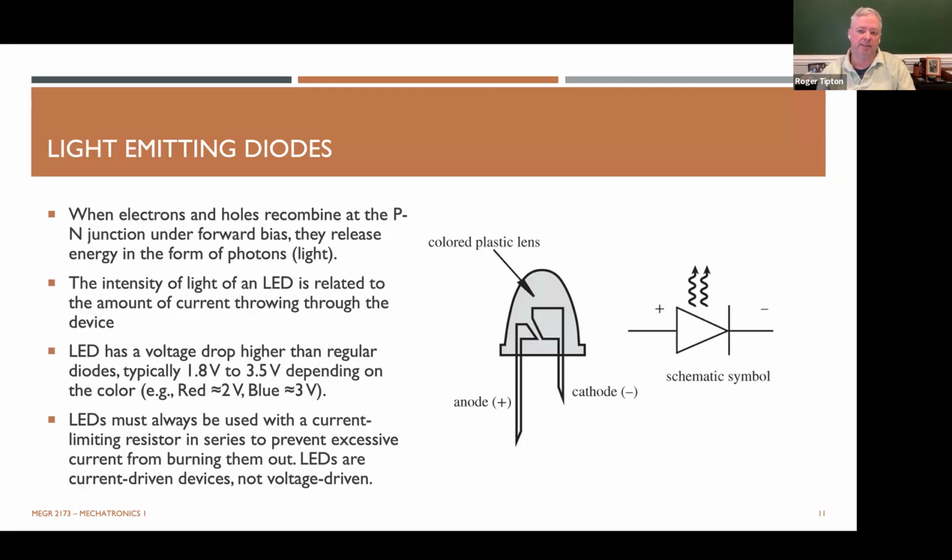So it's not that a different amount of power creates a light, and you'll see that this can be a bit confusing. A red LED, for example, takes 2 volts of forward bias to get the electrons to cross the depletion zone and hit the other side and then emit light.